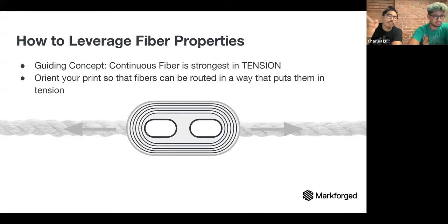And when we make the load bearing material, this concentric reinforcement fiber, anything like bending, even torsion in some cases, is putting tension on the material. So it is really about leveraging your design skills to adjust your design such that everything is in as much tension as possible. And it's actually easier than you might think.